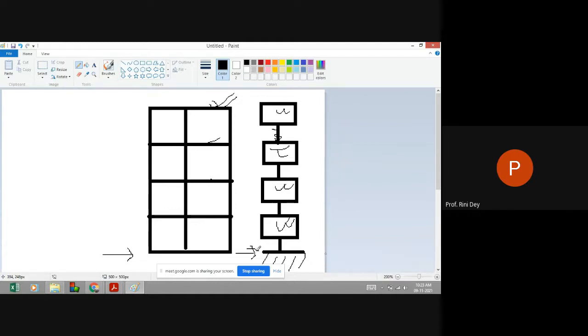There will be a displacement in the ground also, because a ground motion is occurring. If a building's reference point was originally here, due to ground motion it has moved in such a way. It has displaced in this way. So there will be ground motion as well, but due to its fixedness in the ground, the most susceptible part to motion will be the roof of the building. So the inertial effect on each and every mass will also be different.